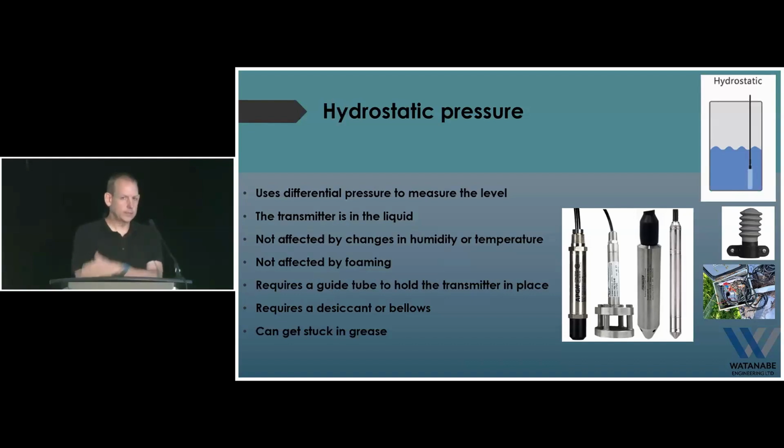And hydrostatic, there's two ways of measuring level with hydrostatic. I'm going to touch mostly on the submersible level transmitter here, but if you're in water, you can also do it where you have a pipe off the bottom of the reservoir and measure the pressure at that point. But both technologies are the same. Ultimately, what we're measuring is the difference in the pressure from where the transmitter is to atmosphere.